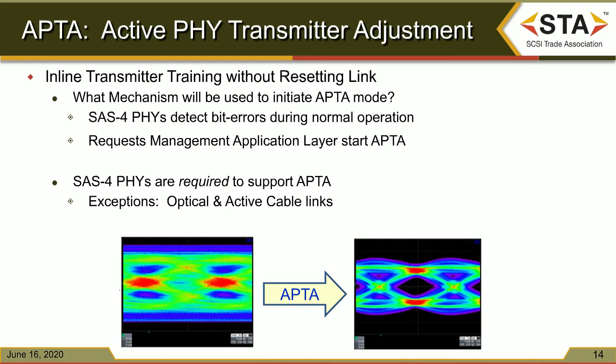One of the disadvantages of that, or one of the problems we found over time, was the system is usually cold at that point in time. The disk drives are not spinning prior to you doing the first link up. Your GPUs aren't executing code. Your processors aren't executing code. And we find that over the next few minutes, the system actually gets warm, gets to a different temperature than the one we negotiated at. And temperature is one of the factors that impact dielectric and silicon receiver parameters. And so we find it sometimes drifts a little bit off its optimal settings.